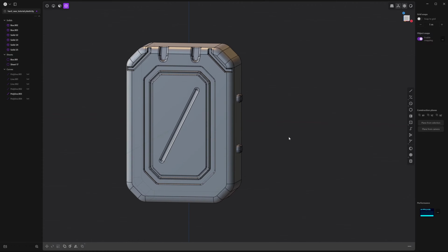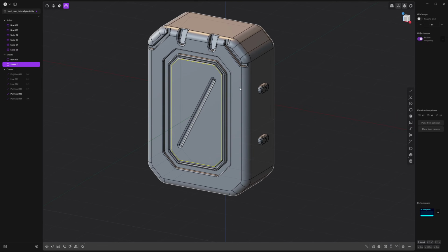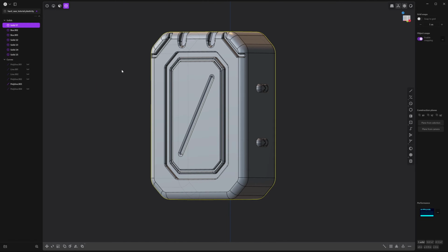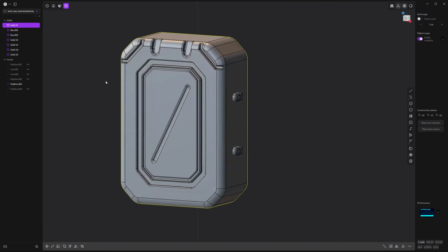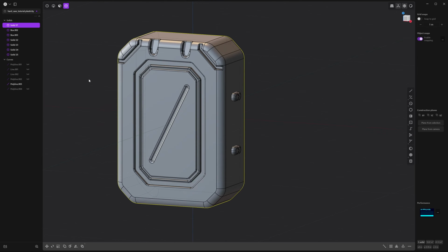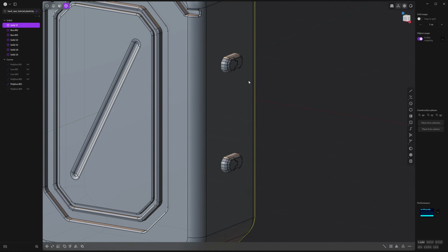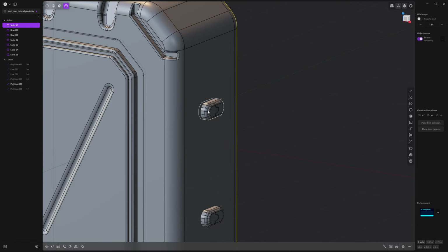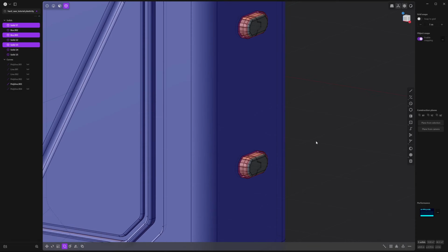before we move on, we want to merge this back together. So select this front face here, shift select the main body and press J. So that'll join them again and that'll create a solid. It's important to create a solid sometimes because booleans might not behave in the way you expect them if they're not completely unified as a solid. So now we can create a Boolean difference using these new objects here for the latches. So make sure you have your main body selected and shift select these two scaled up pieces. Press Q and right click to accept.